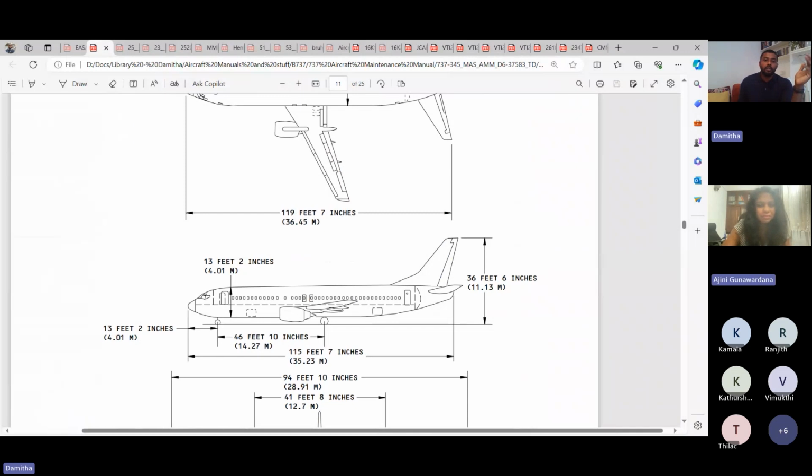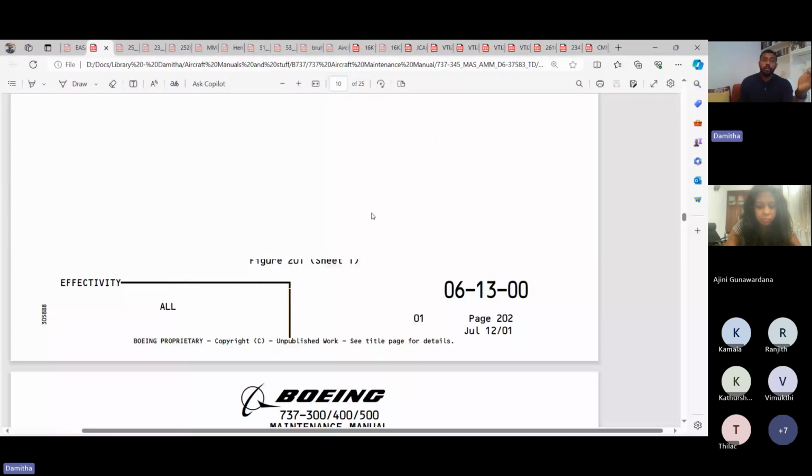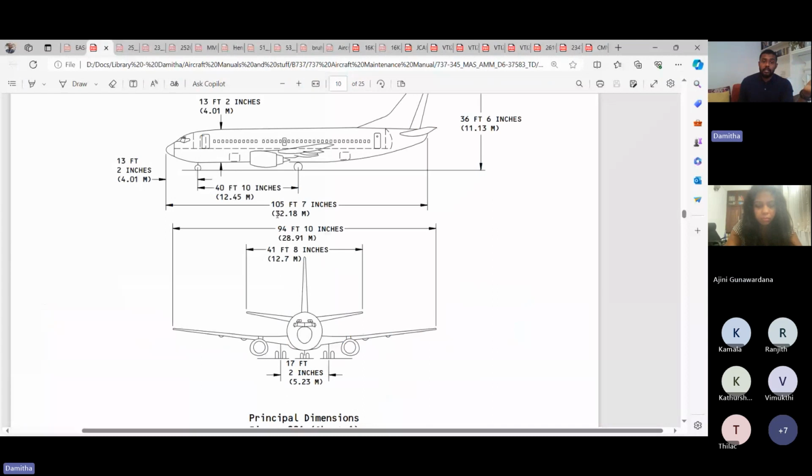As I told you, it's defined by coordinates, and it can pinpoint a position on an aircraft, which lets them know where you are doing the repair or modification. This is how you instruct someone to get into that place and do the design change or repair or modification.